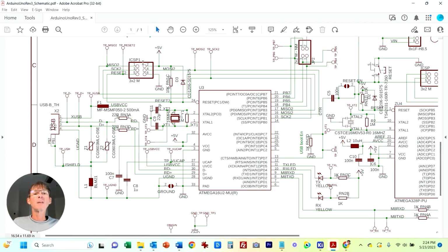So that means at least the first time, and if you're not using the Arduino IDE specifically, then you'll do this every time, you'll program it through the special port that requires a special external device called a debugger. You'll see it called an in-circuit serial programmer or in-circuit serial debugger.